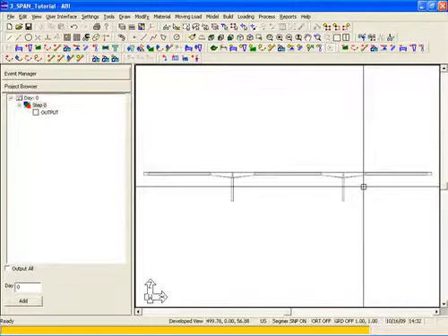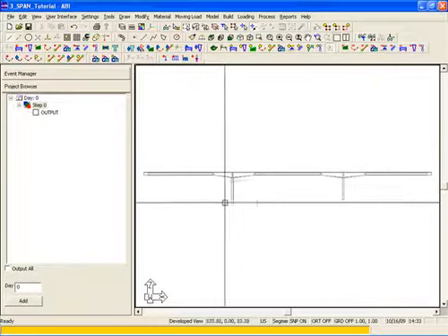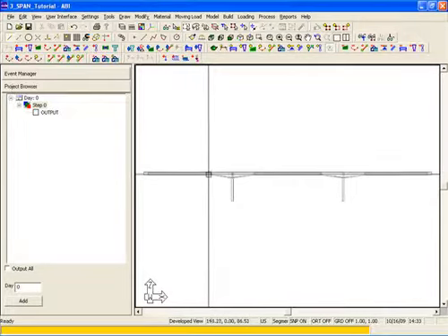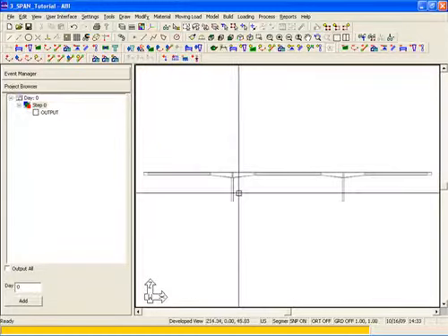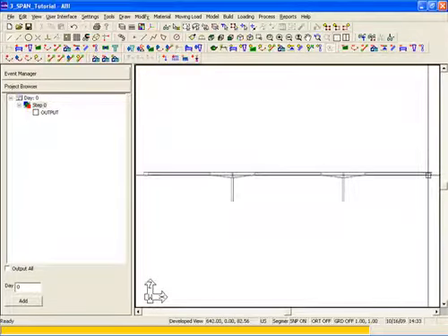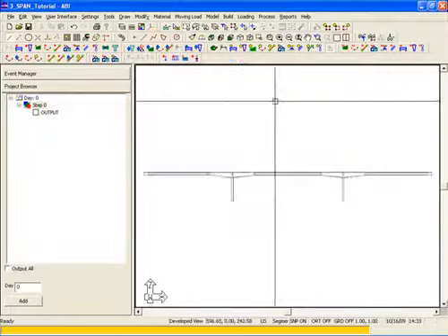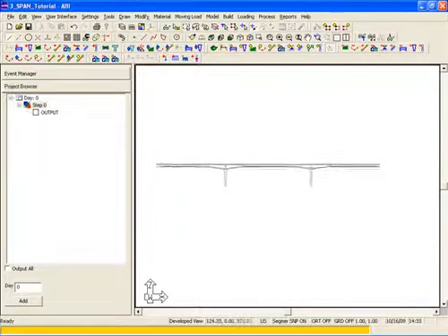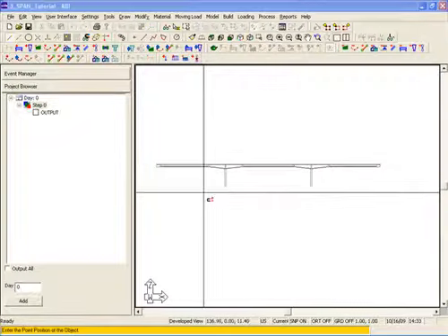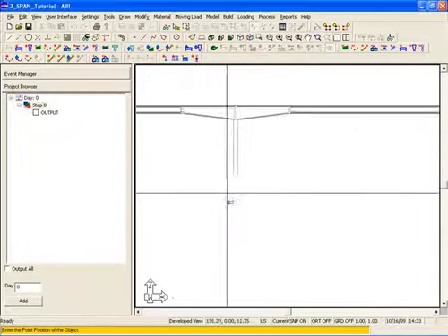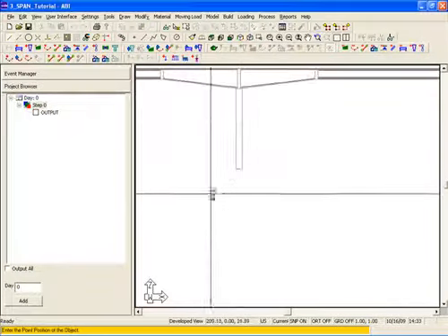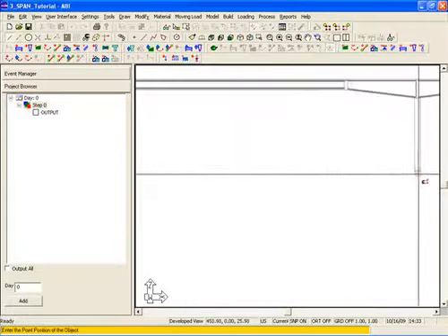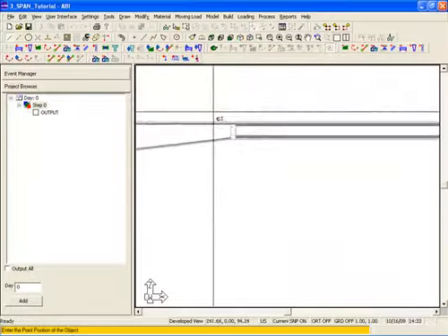To begin, we want to add the supports at the base of the piers, at the temporary locations, for example on both ends of the drop segments and ends of the haunch segments over the piers, and also at the abutments. To add a support, we'll go back to Developed View, and we're going to use the Add Support tool. The default support is a hinge support. We'll begin creating those by placing them at the piers and also at the drop-in segments.